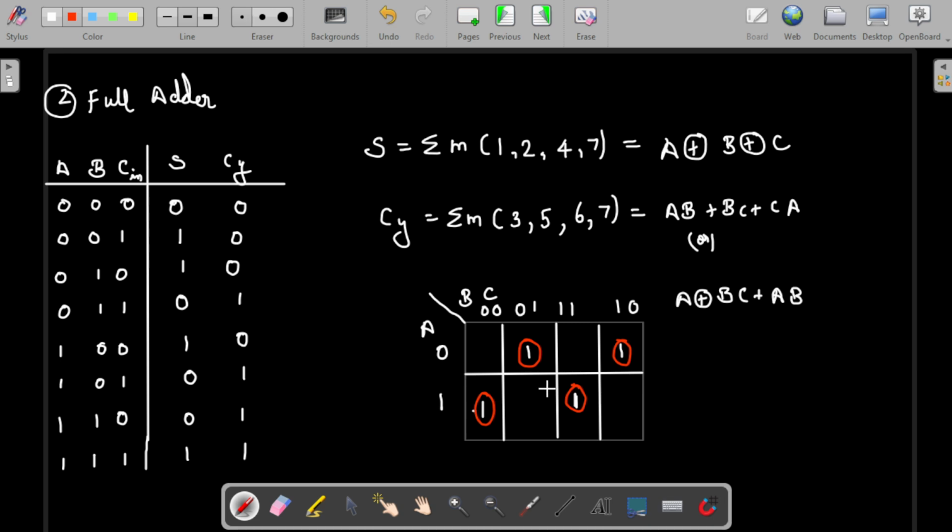But one thing we can do is remember that whenever these kinds of distinct logics come, we can understand that this will be an XOR. You can note this or remember it, because it will simplify your calculations. Instead of going over everything, whenever an output logic comes like this, we can directly represent it with XOR.